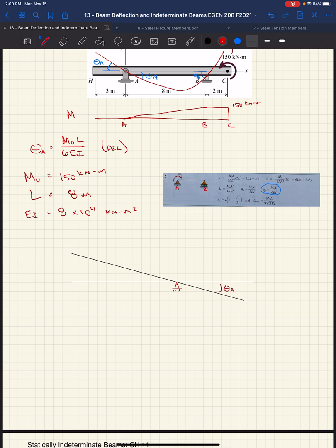All right, we're calculating theta A. Well, theta A is going to be the same on both sides. Complementary angles. And we know that our deflections, based on knowing the slope, is just the slope. We have no applied loads, so this member is going to maintain a straight section. It doesn't bend because there are no applied forces. We can then say that the displacement at H is essentially the slope times the length. This is L. And we'll finish that up on Wednesday.